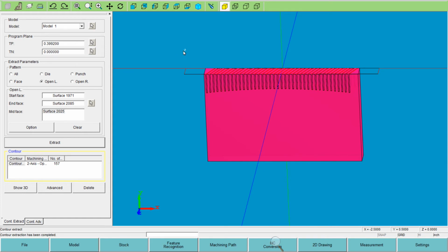Now the start hole has to be perpendicular to this contour. It can't be parallel with it. You have to have a Y number, like I put in. If I had just put it at X minus 3 inches, Y 0, it won't work. IQ requires the start hole to be perpendicular to the face that you're going to approach onto, which is the first element in the feature recognition, okay?